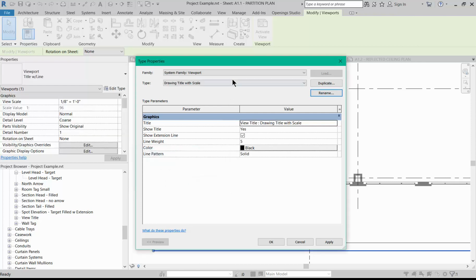Now, one thing to keep in mind with all of these is that sometimes, like you can see, I have a leftover here. It's hard to purge the different viewport substyles. It's a quirk specific to Revit, so don't create a whole bunch of extras. If you're changing them, just override them.